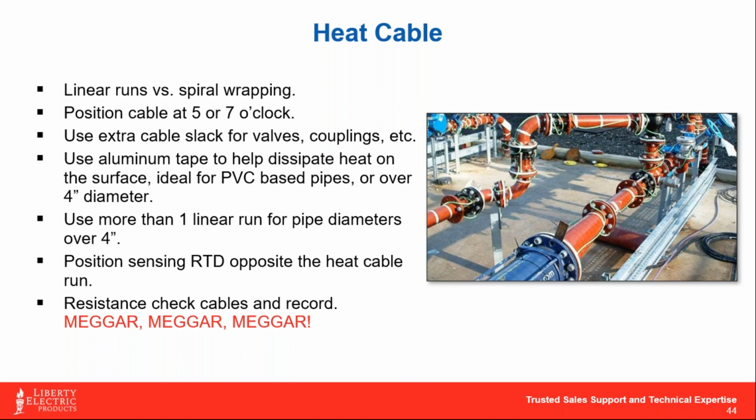It's a great way to ensure that your install is going to be successful by just testing that cable and ensuring that there are no ground fault interruptions. Unlike a process heater, you don't have to put a process heater on a GFI rated circuit. I think some facilities do it as a safety measure, and that's a good thing. But heat cables do require you to be on a GFI circuit. So we want to make sure that no voltage is leaking to ground when we install these systems and cause nuisance trips. Again, that's what the Megger is going to help you prevent.